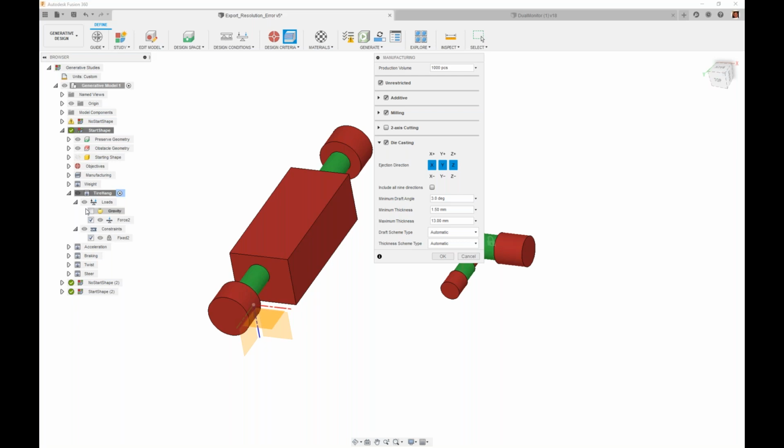So if the loads are happening in such a way that you could take a slice of that extruded part and constrain it, you could look at that from a two-axis cutting perspective. It'd be similar to taking a 1-inch segment of a 100-foot-long gutter and putting loads that may happen in that plane.